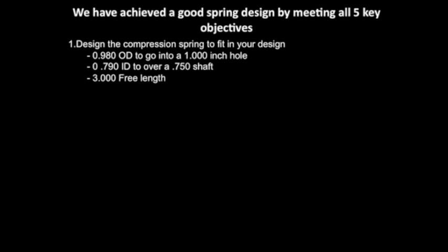We've achieved a good spring design by meeting all 5 key objectives. We've got a 980 OD to go into a 1-inch hole, a 790 ID to go over a 750 shaft, and a 3-inch free length.